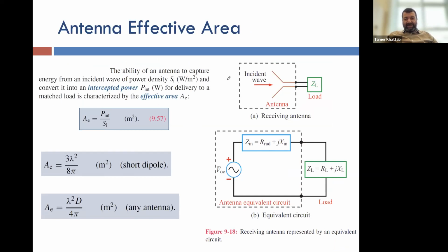Now, I mentioned that in the last lecture we discussed the properties of antennas, but we left a couple of properties to be discussed in today's lecture. The reason is that the property we will talk about today has to do with antennas that have a considerable dimension. You cannot really figure out this property for an antenna which is very, very small, such that you consider it without any considerable dimension or size, and that was the case for the Hertzian. The property we'll discuss today is very important in the analysis of a communication system, and it's called the effective area of the antenna.